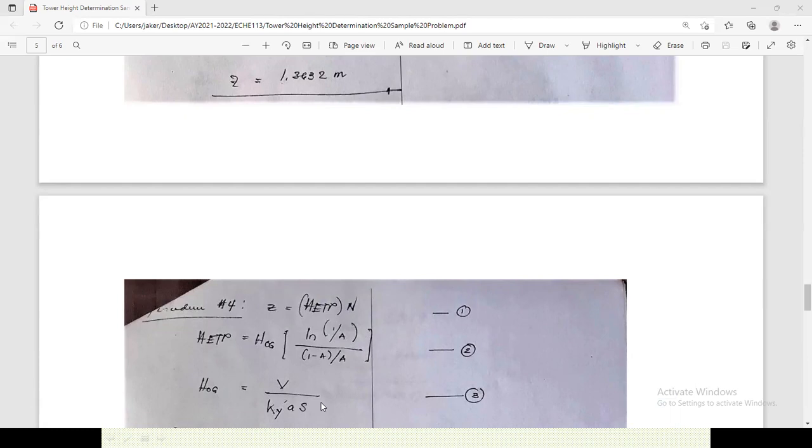You already have the y1, x1, y2, x2, so you just determine the slope. So if the two slopes are comparable, let's say one is 1.185, another one is 1.182, 81, or 79 even, that is more or less okay. Because we can consider that our lines are more or less parallel. But in terms of accuracy, of course, your answer using this procedure will not be accurate because a slope of 1.185 is really different from 1.183 or 180 in that matter.